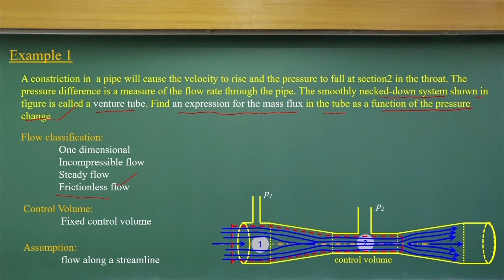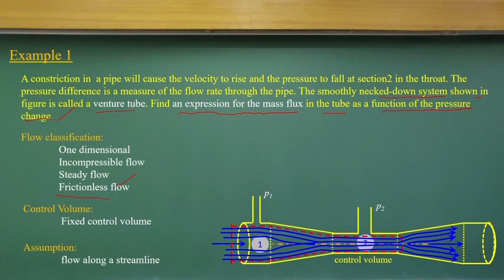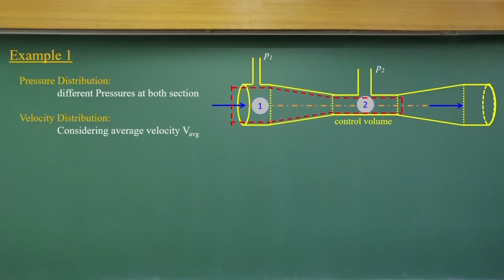The streamline shape could be like this. Okay, there will be converging zones and diverging zones. The streamlines will be converging and diverging. Or if you put in virtual fluid balls, you can track the flow path. The path lines of the virtual fluid balls also could be like this. They will converge, and be more or less parallel in these regions. So, there will be no curvature of streamlines in these regions. Then there will be the divergence of the streamlines. So that is the flow structure we get in a Venturi tube, and we need to compute it